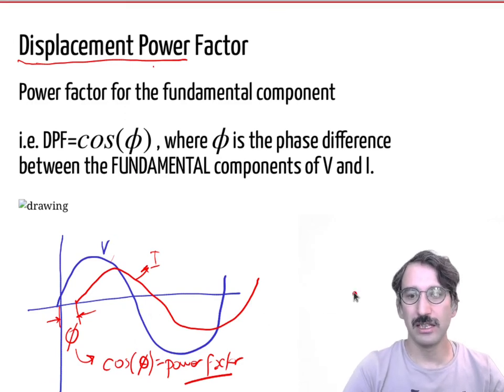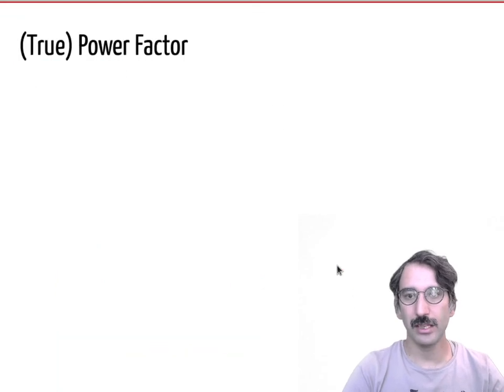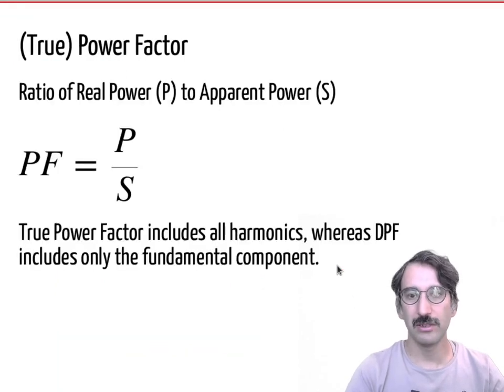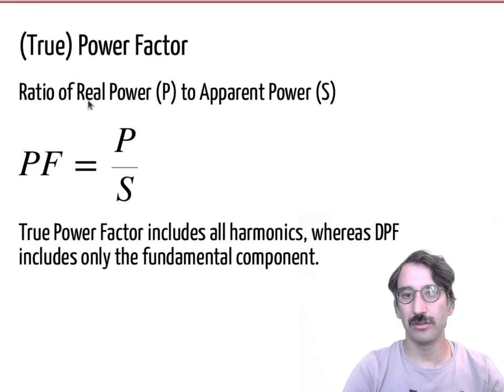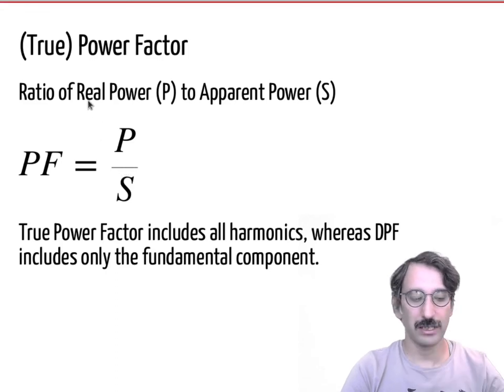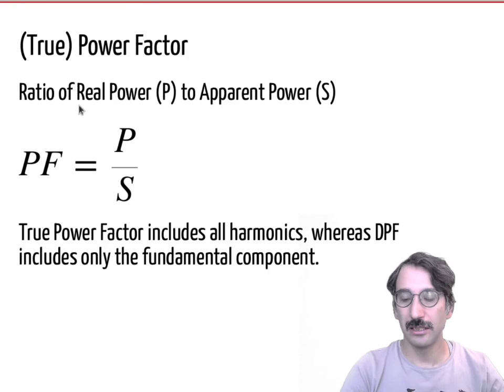When we say true power factor, what we mean is the ratio of the real power to the total apparent power, including all the components. So when we say power factor in this course, we mean the true power factor, but if you are looking at the fundamental components, you need to understand the displacement power factor.